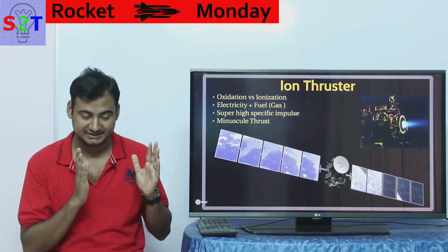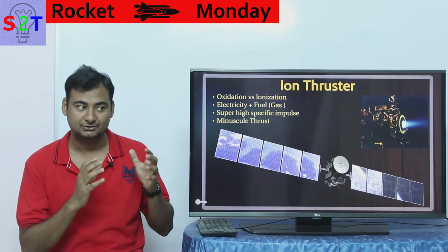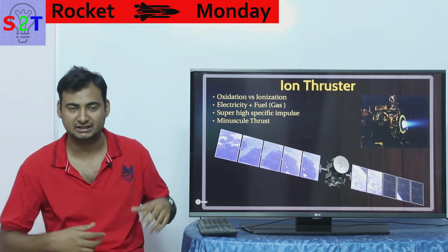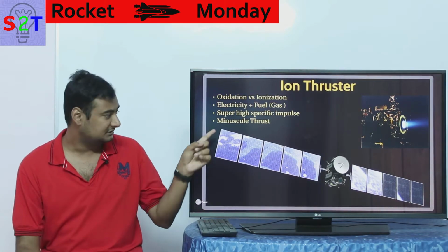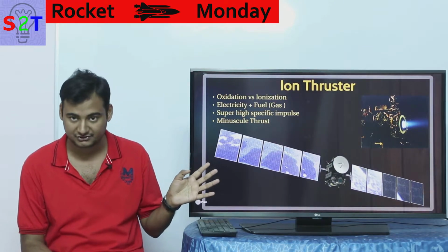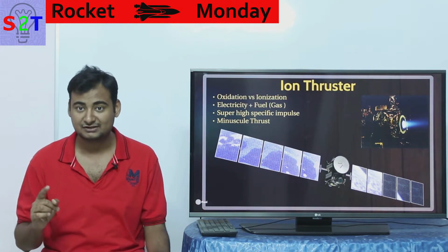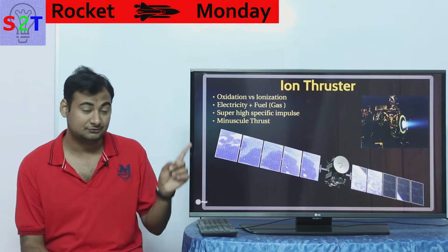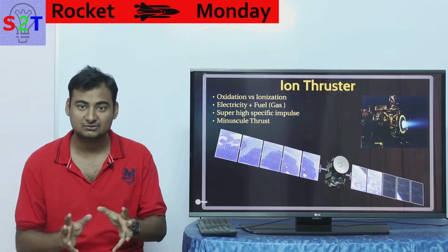If you are familiar with rockets, everybody is saying it has 500 kilonewtons, it has 1 meganewton, and big newton words. These are micronewtons of thrust. Basically, if somebody can build an ion propulsion that can give you 1 newton of thrust, it would probably be consuming hundreds of kilowatts of electrical energy. So be mindful, the thrust out of it is very weak.